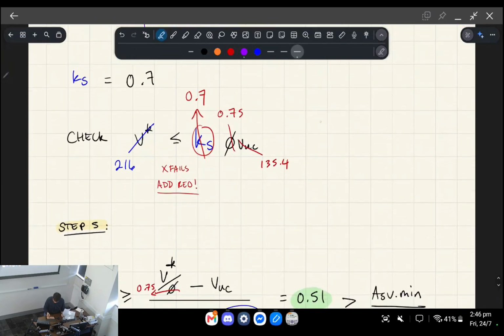And what you'll find is that even without the additional reduction factors, the concrete by itself is not going to be able to resist the shear forces that we apply onto the beam. So what we need to do is add reinforcement, okay? What we were doing a second ago is concrete, no reinforcement, doesn't work. We need to add steel, we need to add stirrups, okay?